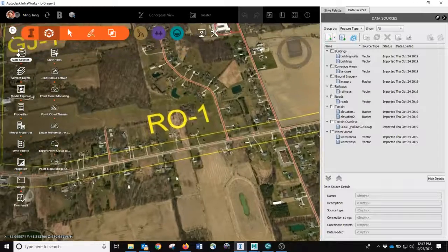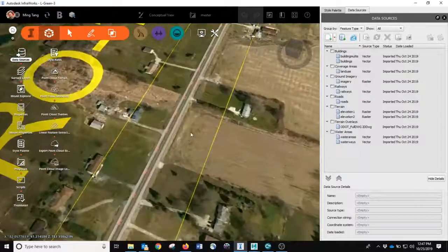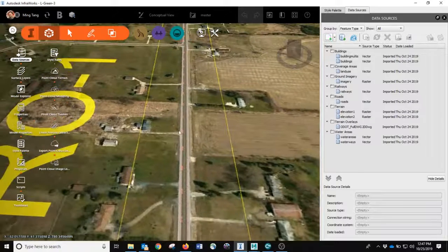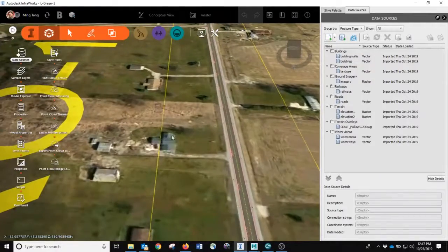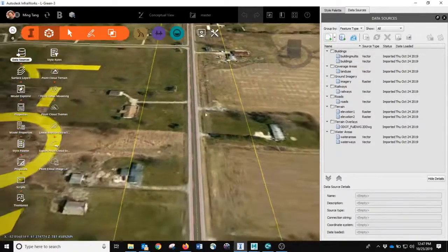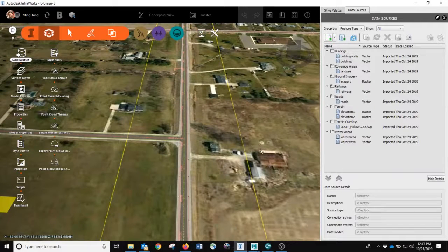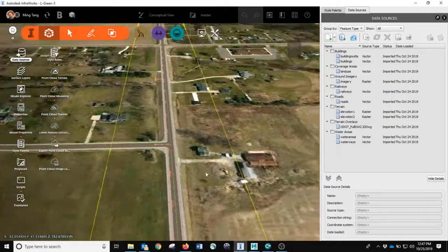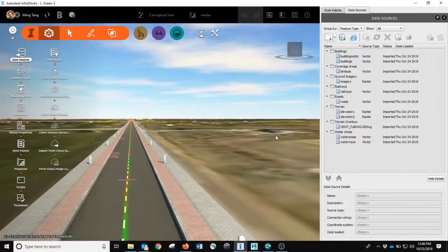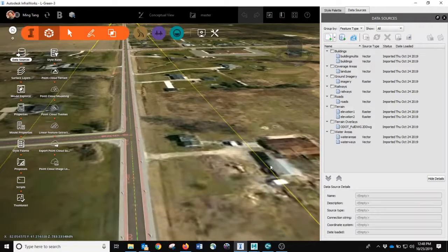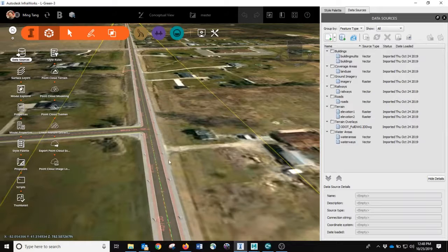And everything falls inside this rectangular box, which is basically 100 meters offset from both ways. You should model it, for example, the building inside, or tree inside, or utility pole inside. If some building is on the edge, maybe you want to model this anyway, because it may be quite visible from the driving simulation. So I want to see that building, even if it touches the yellow line. Okay, so those are the boundaries you want to focus on.